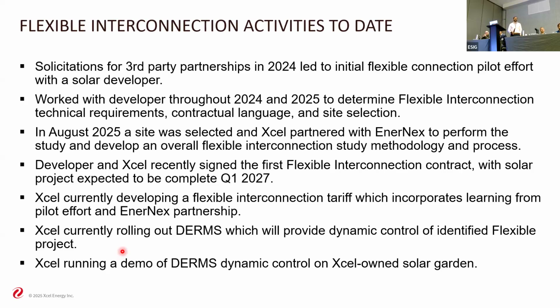Sorry. When you say community solar, the question then is, yes, assume everything is deployed. Would the community solar be factored into the economic dispatch and unit commits, just like a nameplate generator? Yeah, it's a good question. So again, today, most of the DER in the states we operate passively. So there's no active dispatch or no active curtailment. I would even go so far to say that it's not considered as part of the overall wholesale commitments in the markets we operate in.